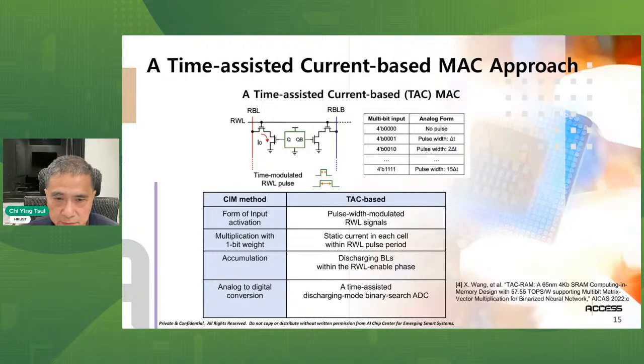Also in this design, we propose a new way to do the ADC without a dedicated ADC. We use the bit line and bit line bar to do what we call discharge-mode binary ADC, which we are going to talk about more later.